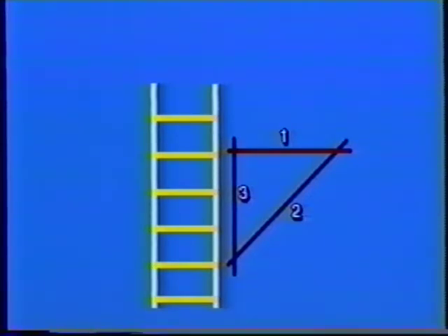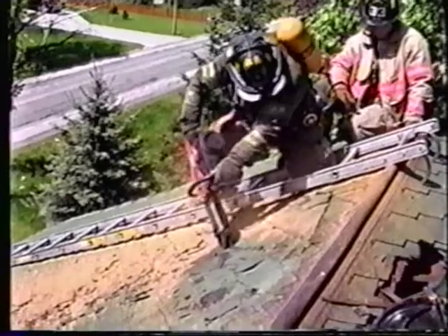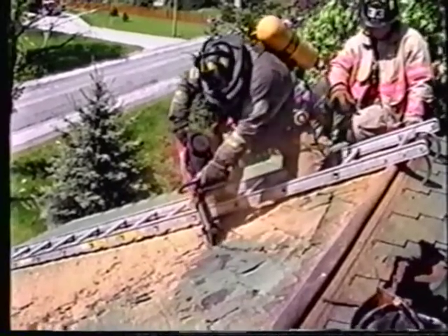Here too, a knockout can be included, but unlike the knockout for the standard cut, it is nearly impossible and in fact dangerous to attempt a knockout cut at the far corner of the triangle. With any roof cutting operation, avoid overextension.